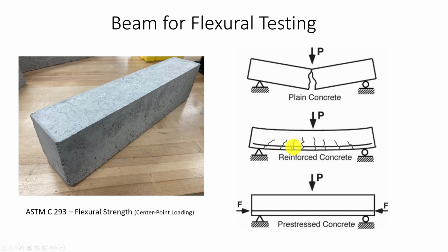Now, once we put the reinforcement bar in there, we're going to probably see potentially more cracks forming, but that's not breaking as much because that bar is taking that load, and then eventually it's going to fail. So the machines are set up to tell us the point that it's reached its maximum load, and it'll give us that data. So that's pretty much it for this portion of the video. Just wanted to take a little bit of time about the products that we're going to be making and what we're going to be seeing in lab.